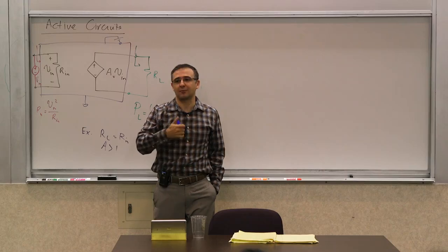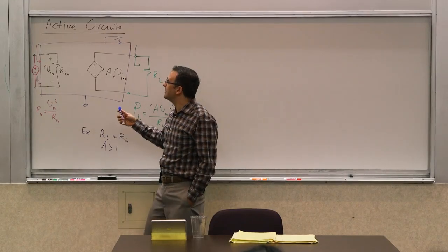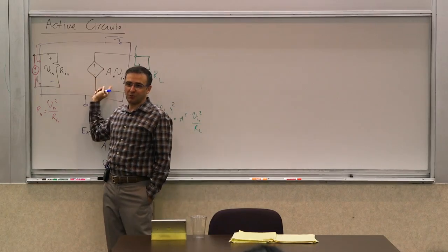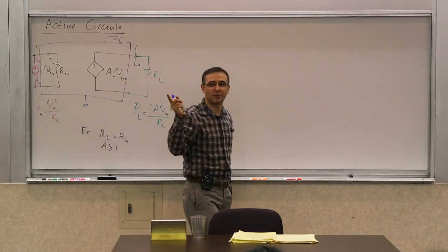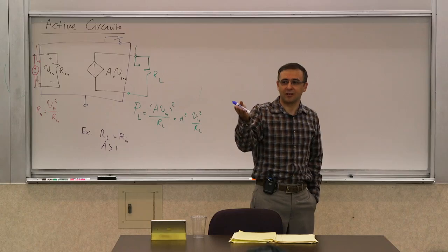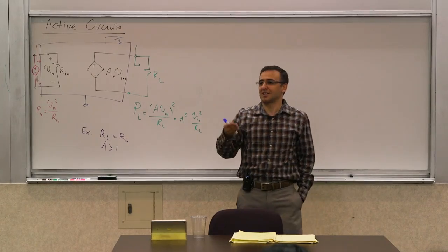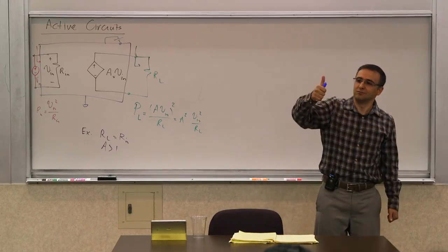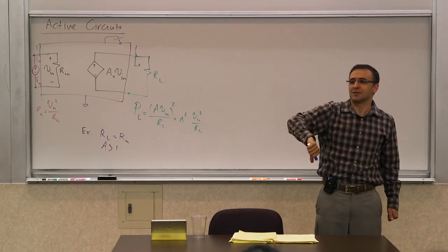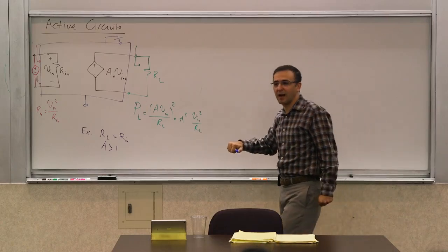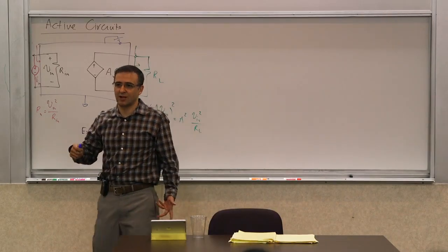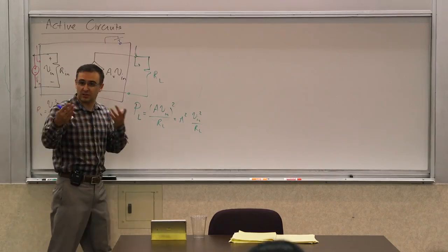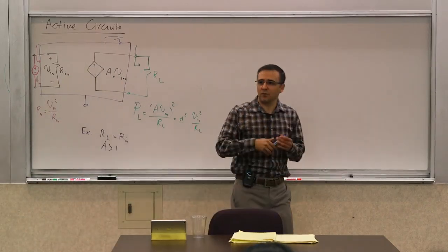The way it happens, and I'm jumping ahead a little bit but that's okay, is that yes, you can increase the voltage, but you're paying for that with something else, which is the current, right? So the product cannot increase, which is the power, the product of the voltage and current. So yes, you can jack up the voltage, but then the current will go down at least by the same factor. And if you have loss in the transformer, it will go down by more than that factor. So that's why I got into it. But it's a good comment, so I wanted to make that distinction.